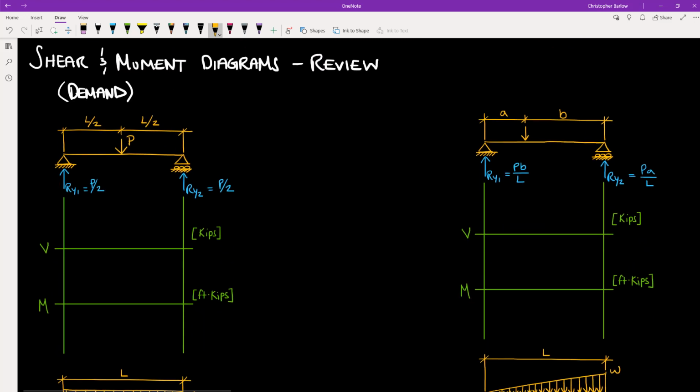Now, with perpendicular forces, we need to pay close attention to the difference between external and internal forces, because our internal forces are going to change. As we saw in the foam demonstration, the internal forces that we created with our externally applied force, our little matcha tea canister with the coins in it, those internal forces could change depending on the location we placed our weight. Even though we weren't changing the magnitude of the applied force, the internal forces were changing.